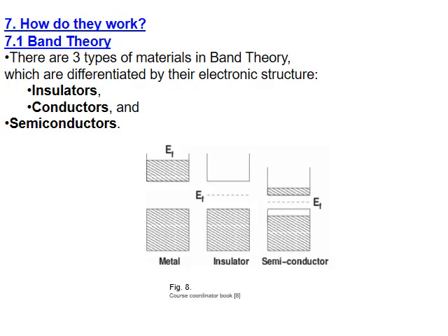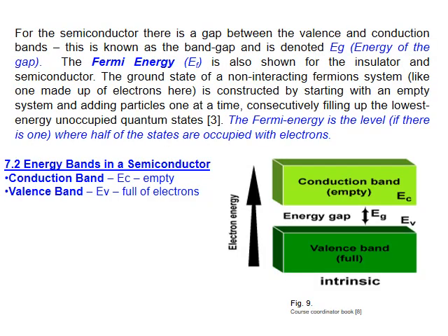Now, as I mentioned, we have insulator, conductor, and semiconductor material. In the metal, which is the conductor, on the atom level we have a valence band and conduction band in any material, and the gap between them is the energy gap. In the conduction band there are some electrons. In an insulator, it's empty, as you can see here. But in a semiconductor we can create a few electrons here, and it will be close to a conductor.